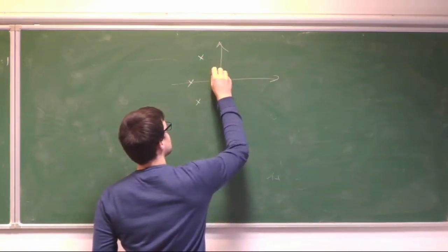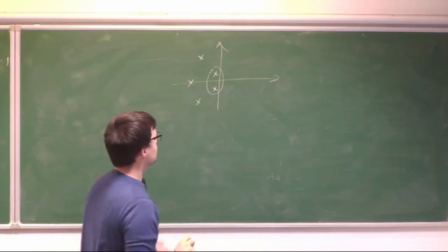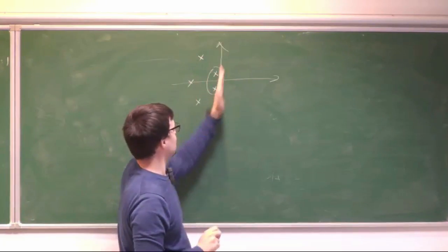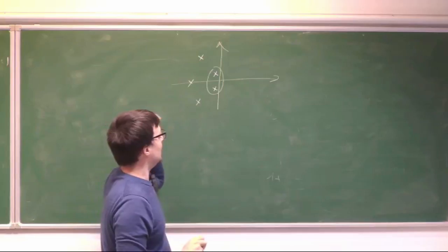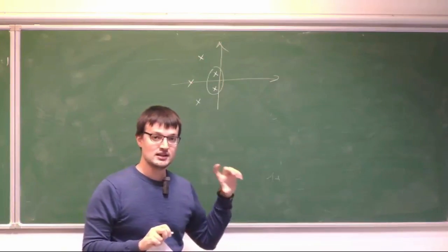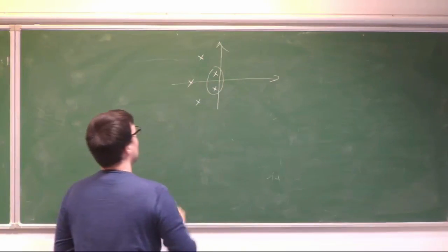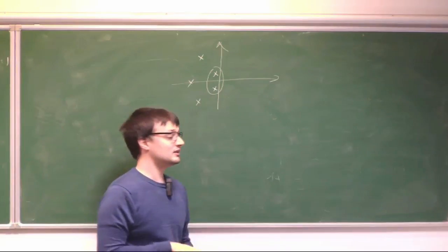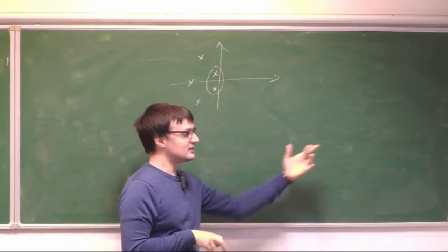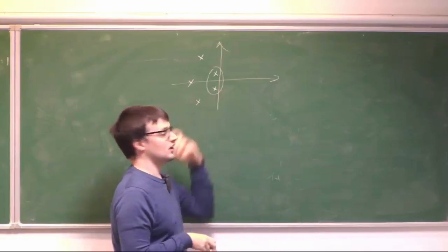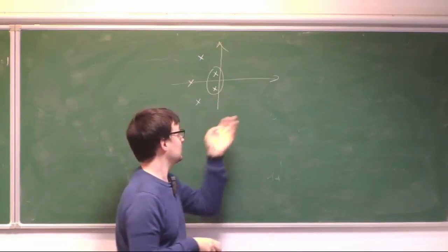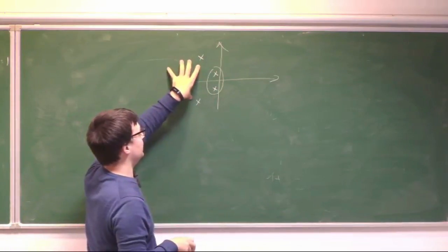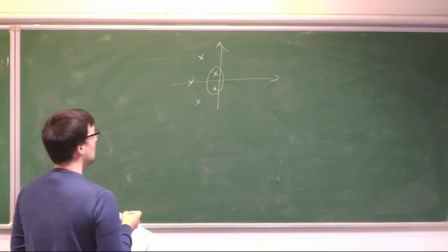The dominant poles are these poles over here, okay? So they are the slowest poles, okay? The closer you are to the imaginary axis in continuous time, the slower is the response due to that pole, okay? And so it means that these are the slowest, and those are the dominant poles. The reason why they are dominant is because the steady state will not be reached because of these poles, because they are the slowest. Okay, so they are the dominant poles. The effect of these other poles is going to disappear much faster than the effect of this pole. Okay, so we have those two poles.